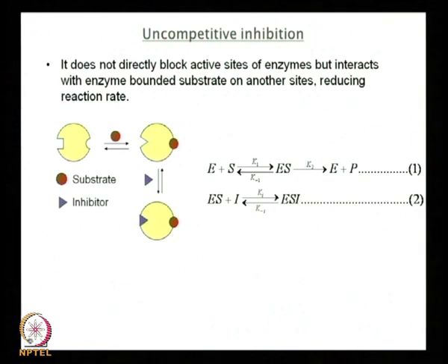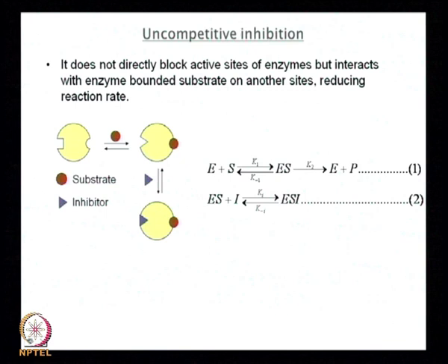Any combination I give you, these are some examples we are doing which are prototypes, but if we go beyond these prototypes and come up with more complicated things, what you have to figure out is, A, what are the reactions that attain equilibrium, B, what are the species that attain quasi steady state, and C, which reaction is the rate limiting step that will govern the rate of product formation, and finally D, you have to figure out the constraint equation.